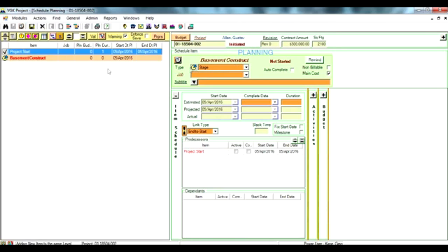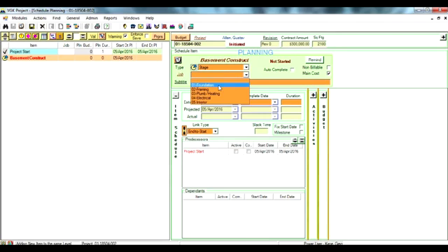Note that the schedule item's name is the same as the name of the typical item. The new item already has a predecessor, the Project Start. And a link type was also set by default. Set as End to Start, meaning that there's no breaks between these items. Here's the item name, and if a job is defined for the project, you can link this item to it. We just set the item duration, and that's all that's required to put an item into the schedule.